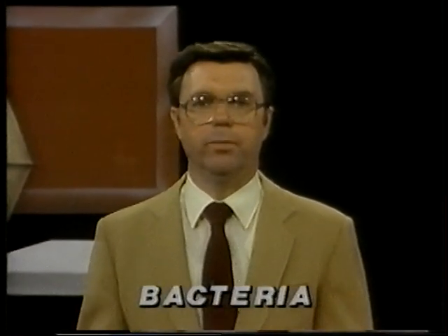Bacteria can grow and thrive under many conditions in soils adjacent to the metal pipeline or the metal tank. One of the most common bad actors we find grows under anaerobic conditions, where we have no oxygen present. There's a strain of bacteria called sulfate reducing bacteria, and part of their metabolism is to convert sulfates in the environment to sulfides. Sulfates are rather innocuous in corrosion reactions. Sulfides can be extremely corrosive. So under the conditions where these colonies of bacteria grow, they actually modify the environment and make it much more corrosive.